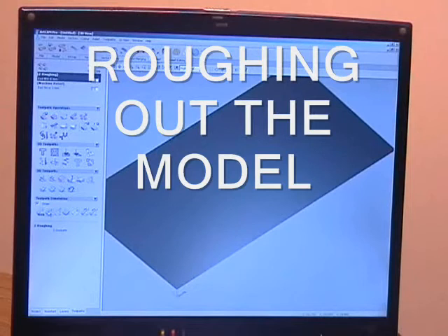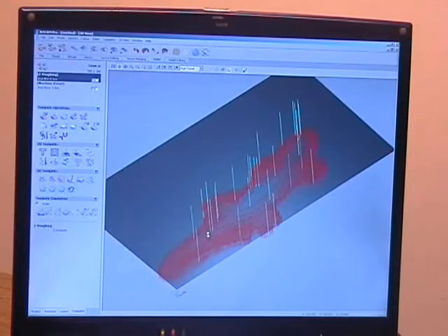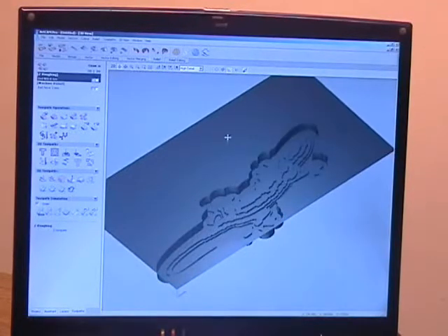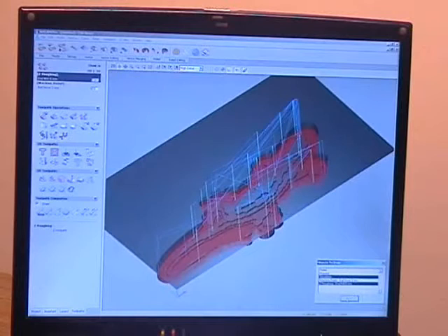First of all, you want to do a roughing pass, which takes out the excess material and speeds up the 3D side of it. As you can see here, the red and the blue indicate the tool marks. I can show it in more detail if I apply the tool path. The red indicates the X and Y stroke, and the light blue indicates the plunge, and these are the rapid moves to different points in the model itself. So that is the roughing side of it.